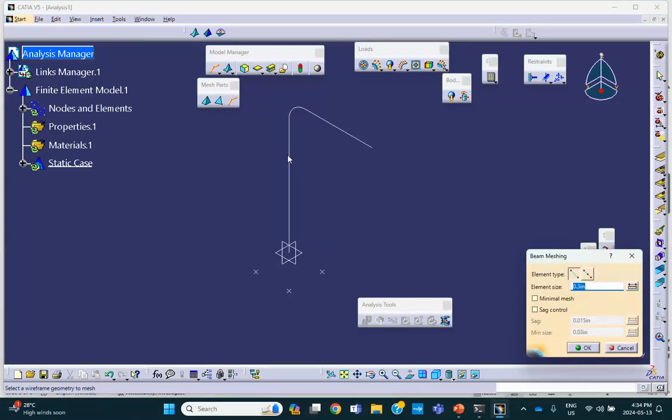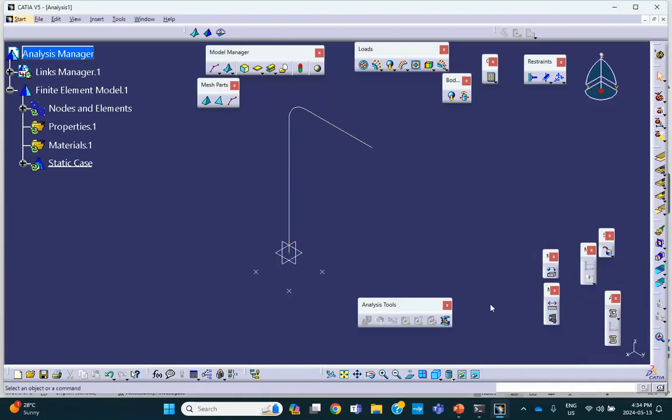Click on this, select this, and we use the same number. You say, okay. So right now, it is the same mesh. The cross section has not been defined yet. So to define the cross section, you have to define a 1D property right there. You see this? 1D property. 2D property is for shells. We haven't done it. 3D property, if you want to mesh something yourself, but if it's done automatically for you, this is automatically created. But anyway, we're dealing with beam.